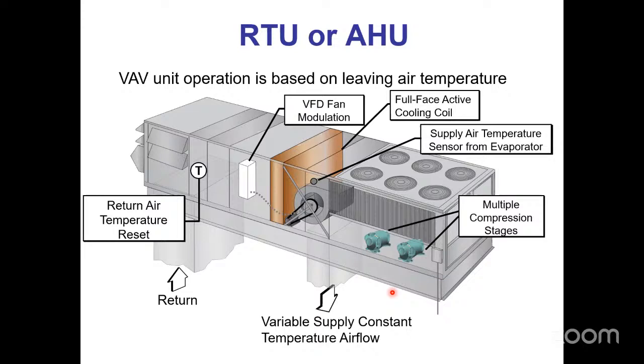And that's all it does, right? 67% for stage 1, 100% for stage 2, that's it. We're using a VFD on staged air volume, constant volume, as a two-speed motor, basically, because two-speed motors with double the windings actually cost more than a VFD does nowadays, so we use a VFD to do that. We are not talking about that. We're talking about a true VFD application where the VFD is going to ramp this thing up and down to maintain a specific static pressure. So more than two speeds. I'm going to have hundreds of speeds, each little incremental one in there. So I need to have that VFD in order to have a VAV air handler. I also need to have a boatload of cooling staging ability. So option 1 is chilled water with a modulating valve.